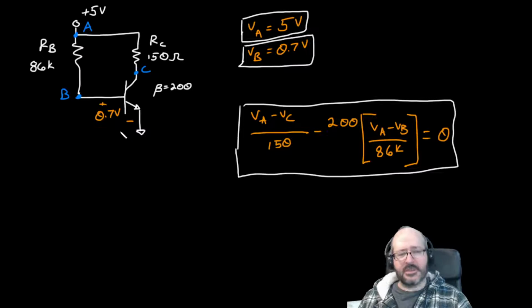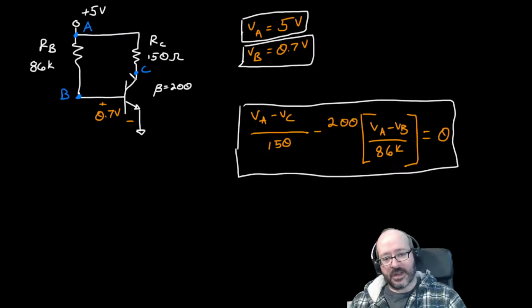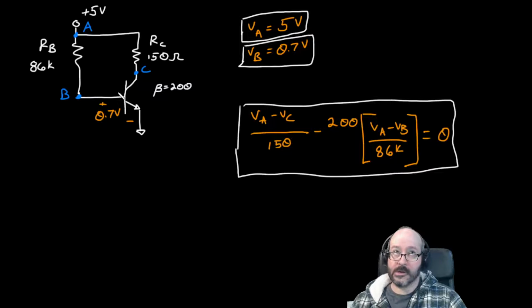The first way, I usually ask the class and let you scratch your heads and try to figure it out for yourself, but you're not here, and oh boy, do I miss y'all. So I want to drop all of the 5 volts across this 150 ohm. I can do that by increasing the current, right? So I times R is going to be bigger. I can increase the current through here to make this drop bigger. I want to increase that current.